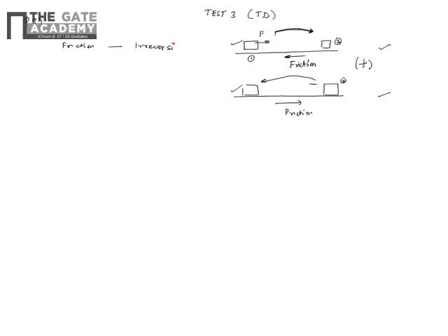This is a simple example to show that friction causes irreversibility in the system. In the same way you can show that unrestrained expansion does too. That is, you have air or some high pressure gas on one side and vacuum on the other side, and you just remove the diaphragm, so the gas suddenly expands. This sudden or unrestrained expansion is also a case of irreversibility. So both the first one and the second one cause irreversibility.